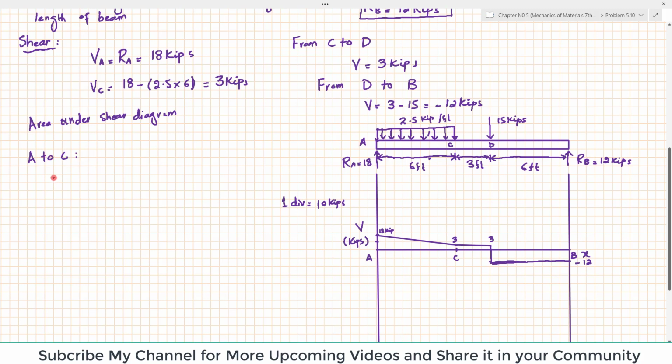we have the area under the shear force diagram, which is the integral of V dx, and you can see this area. This forms a trapezoid. So the area of a trapezoid is 1/2 into base. Base is 6, and this height, which is 18, plus this height, which is 3. Again, when you calculate it, it will be 63 kips into feet.